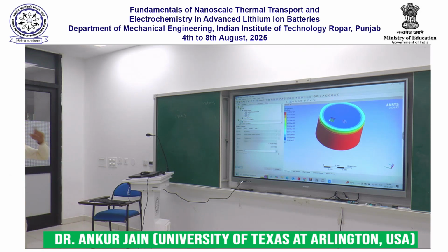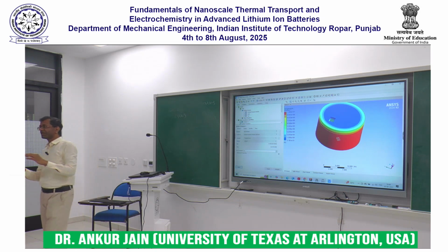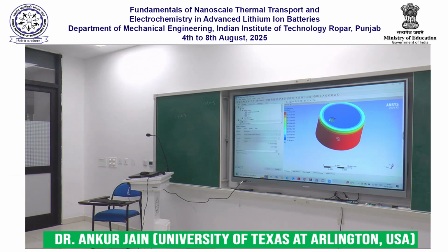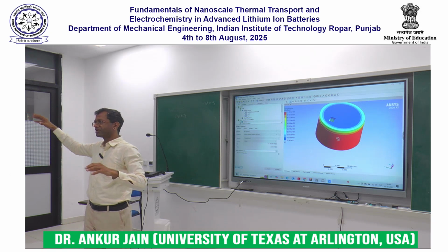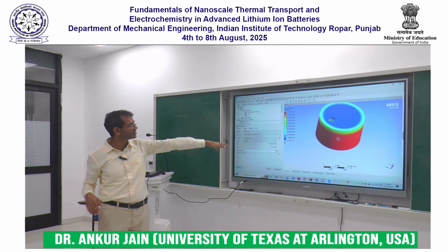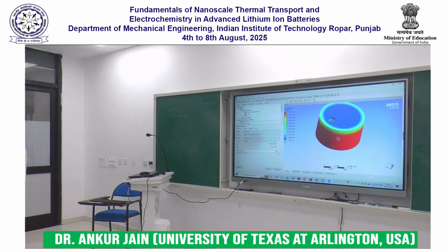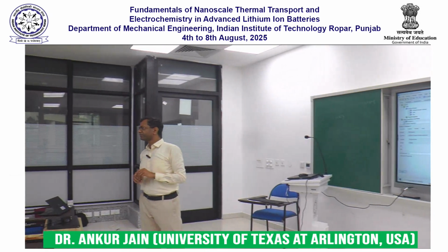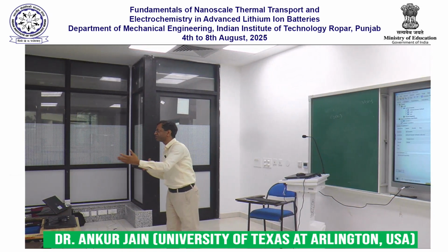You will see that there is some problem here at the boundary between the two boundary conditions, and that is mainly because our mesh was extremely coarse. You can create all kinds of contour plots, two-dimensional plots, line plots, and analyze a bunch of other things using this interface. So tomorrow when we do the next tutorial, I will take up a real life battery problem, and we will solve that battery problem using CFX, and then we will be able to ask a lot of questions to the simulation.